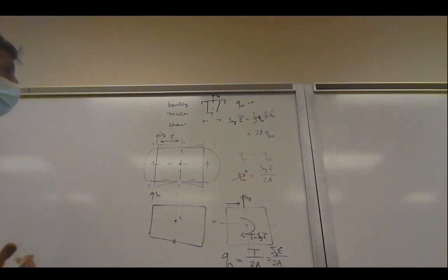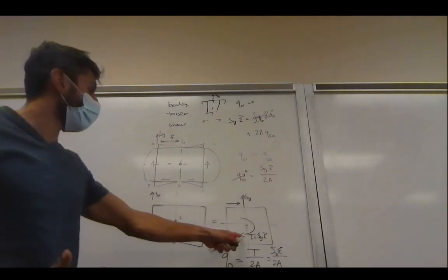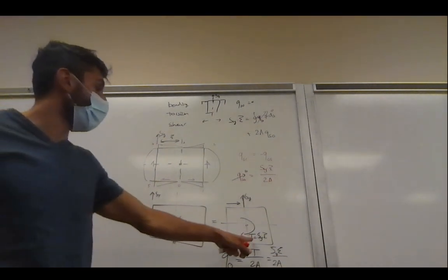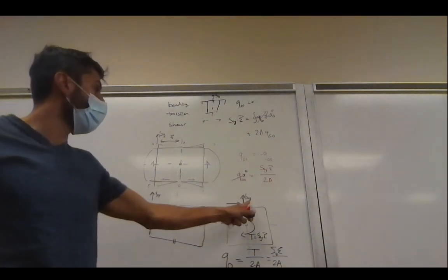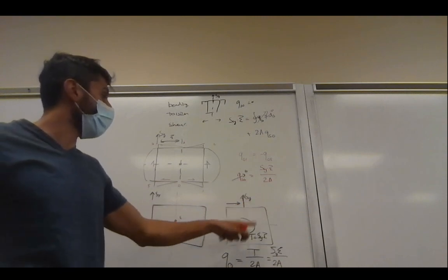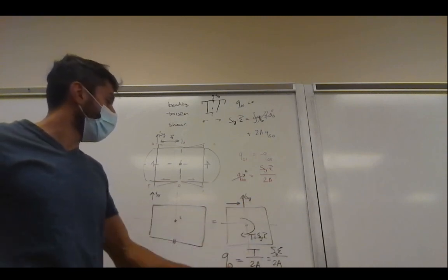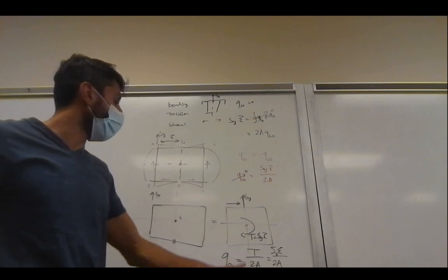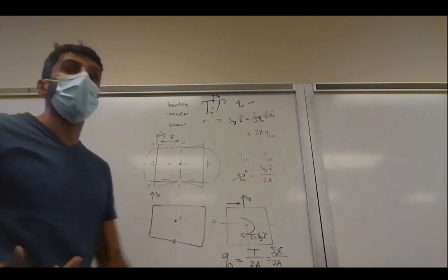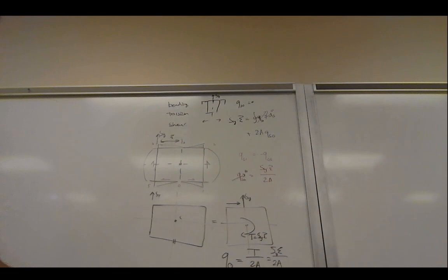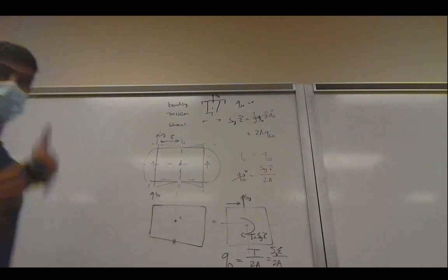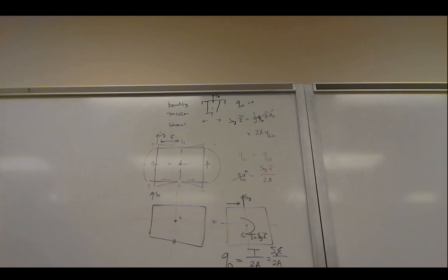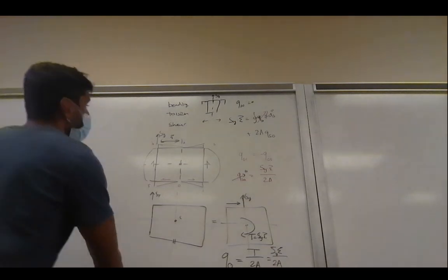And then we can just add, in this case, we can do the same thing and say, well, because we moved the shear force, we have to compensate that with the torque, and the shear flow due to torque is equal to T over 2A. So it becomes a bit easier in some cases. This is a very simple problem, but there are more complex problems where moving the shear force and adding a torque to it significantly simplifies your life in the calculation steps.